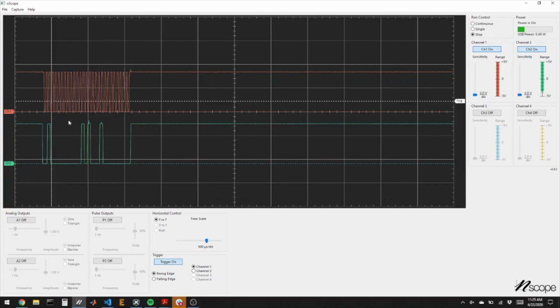So this isn't something you can test without plugging your PIC into a device that talks I2C, because the PIC, when it writes to the chip, if that chip doesn't exist, will hang here because it never gets the acknowledge bit. So you won't be able to test this until the next video, when we'll use our first I2C chip.